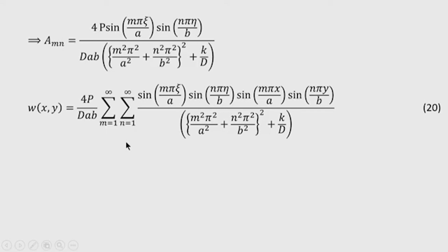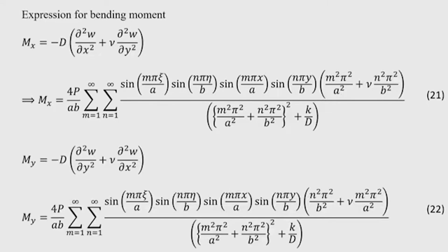So, you get multiple axle loads, that is, multiple concentrated loads. In that case, the deflection at any point can be found by the principle of superposition, because we are only dealing with linear analysis. Once the deflection series is known, it is possible for us to calculate the bending moment expression.